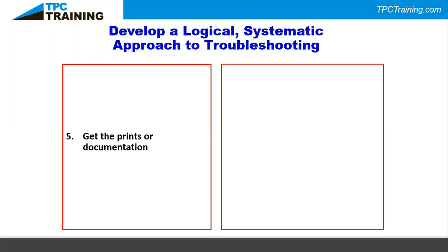Not only that, but if your schematics for your specific machines are out of date for any other reason, you could actually be facing some serious risk. Think about it. If your maintenance technicians are looking at a schematic and expecting, let's say, 2 relays and a motor starter for this machine, and they open the door and they see 5 relays and 4 motor starters, right? That they replaced equipment since the last go around of that drawing. Now that person really doesn't know what wire connects to what anymore and what readings they should be getting from where.